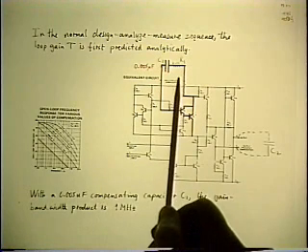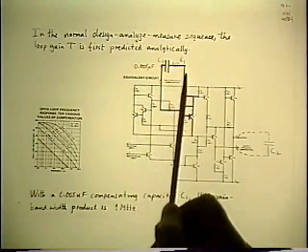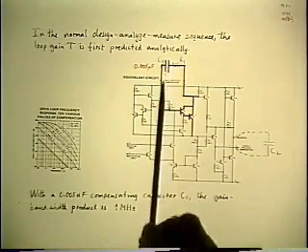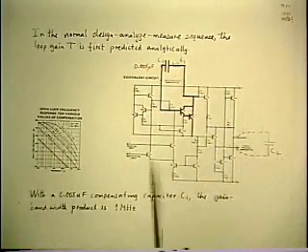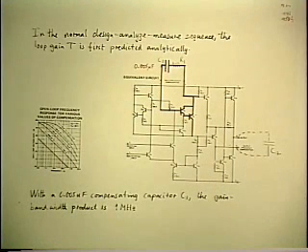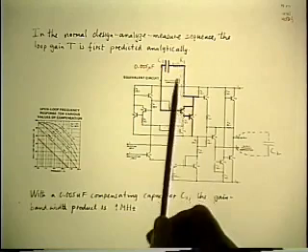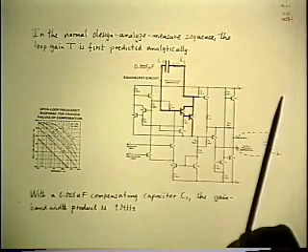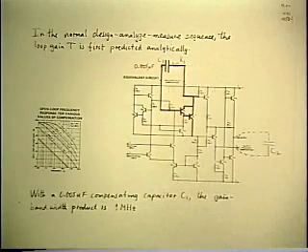Now, when I look more carefully at this data sheet, you see that I did something wrong in the design, because the data sheet said I should have put a resistor there as well. In fact, it's labeled on these asymptotes. I neglected to do that, on purpose, of course, in order to illustrate this point. Because what happens if you put a resistor in series with that cap? It limits the effect of the capacitor. In particular, as frequency goes to infinity, the cap will become a short, and you'll be left with the resistor.